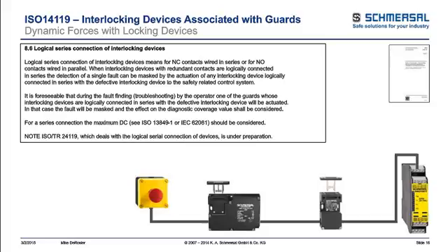A lot of questions come up with daisy chaining because it is one of the most common methodologies you see out in machinery. Their switches are daisy chained to one safety monitoring relay, for example, as you see in that picture.